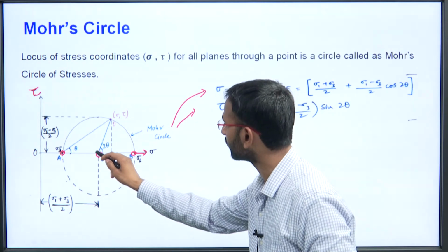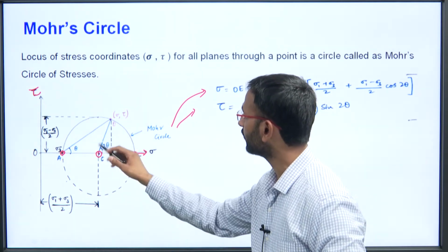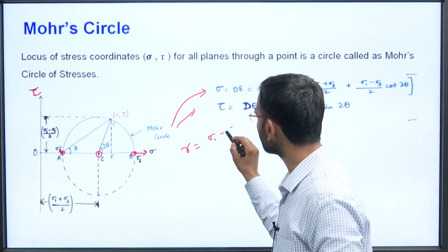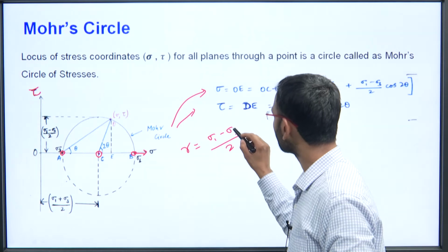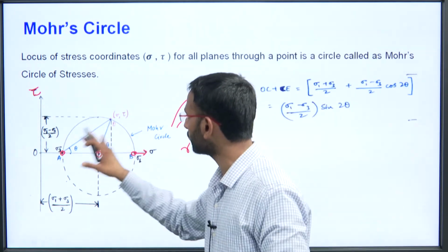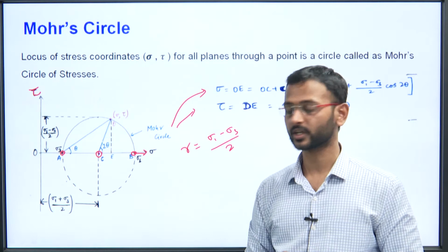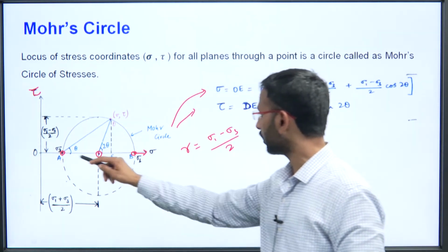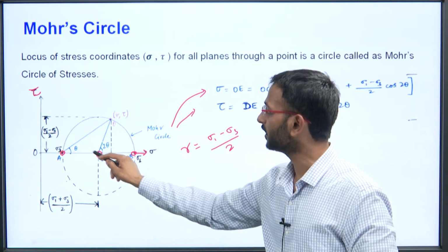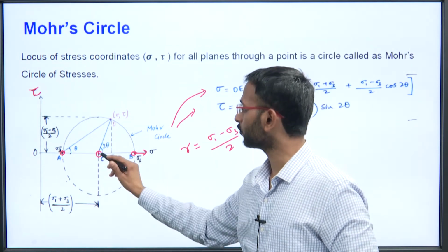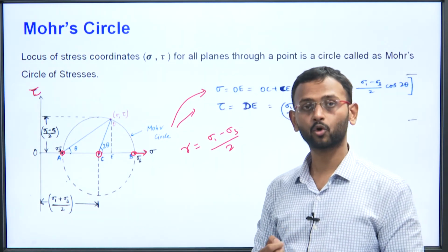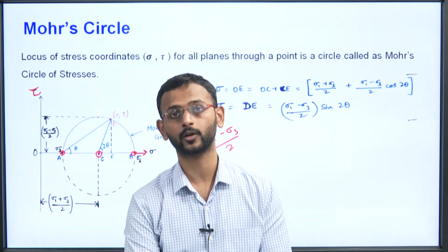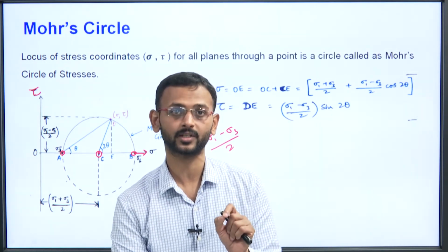We are talking about the center here, alright. So, this is this point, and we talk about the radius, alright. Radius of this circle is what? Sigma 1 minus sigma 3 by 2. So, we can simply draw the Mohr circle and we will be seeing how this Mohr circle is being drawn there. So, the center is at, on the x axis it is what? Sigma 1 plus sigma 3 by 2 distance, and on the y axis it is nothing but 0. So, this is the Mohr circle that we will be considering, and when the Mohr failure envelope will be drawn, at that time also we will be discussing this thing.